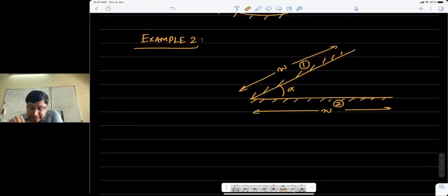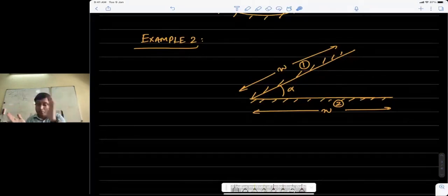So in itself the problem is not complete, because I can see, and I hope that you also agree with this, that not all the radiation leaving surface 1 reaches surface 2. Some of it is lost in this area which we don't know anything about. So that is the surroundings basically, right? You can think of it this way: these two plates are lying in the room, and there is nothing else in the room, so of course some radiation will escape to the room.